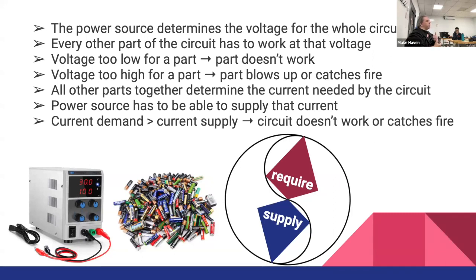Arduinos have a built-in voltage converter that will step down from 5 volts to 3.3 volts, so you can connect any peripheral to it. But the power supply that you connect to the system is a 5-volt system. Similarly, a big desktop computer at home will plug into the wall, get 120 volts, but the various components in the computer might run on 12 or 5 volts, depending on what they need.